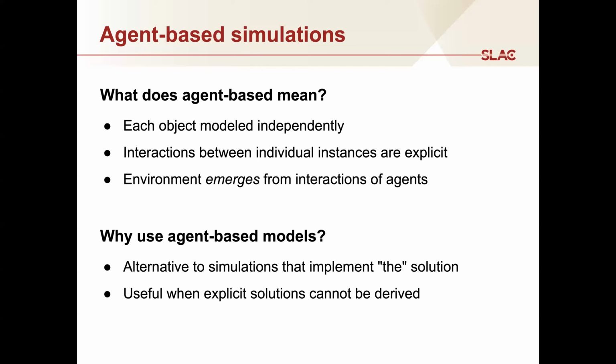So for example, we might have a set of solvers that describes the buildings and another set of solvers that describes the power system. And together they create an environment from which the dynamic solution will emerge. So we don't solve the 2 sets of equations simultaneously because we actually can't. And instead we solve alternating solutions in an attempt to get them to converge to some sort of agreed outcome.